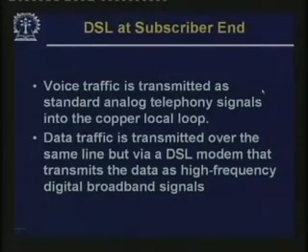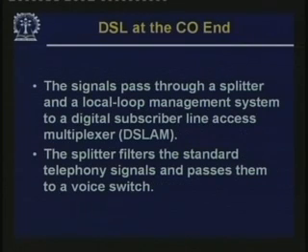So, in DSL at the subscriber end, voice traffic is transmitted as standard analog telephony signal. Data traffic is transmitted over the same line but via a DSL modem that transmits data as high frequency digital broadband signals on the same line. So, if you have a DSL modem, you can have both your voice as well as data at the same time, unlike very ordinary analog lines.